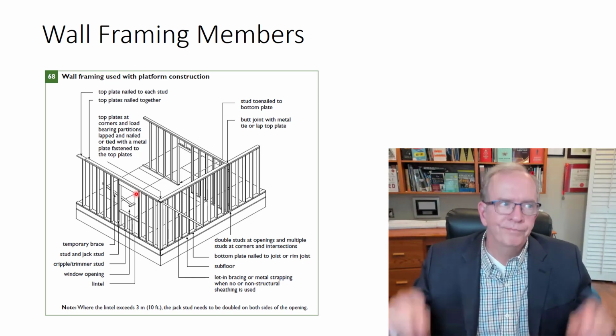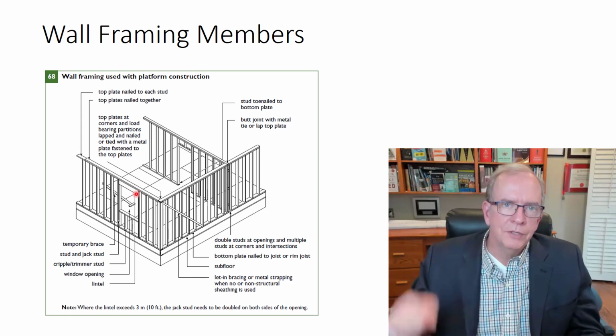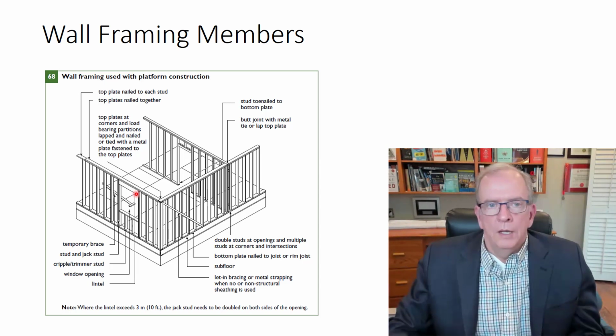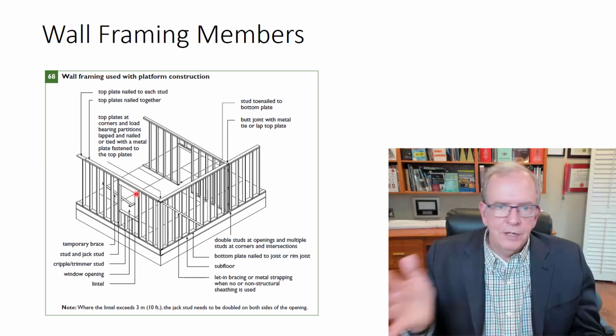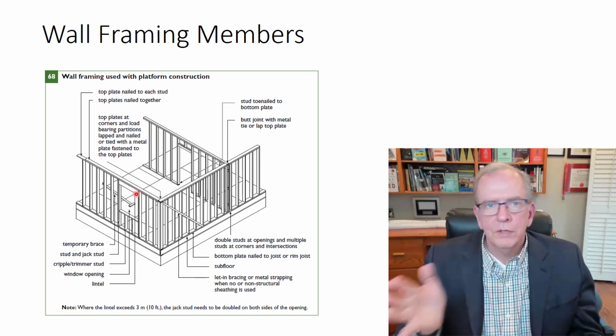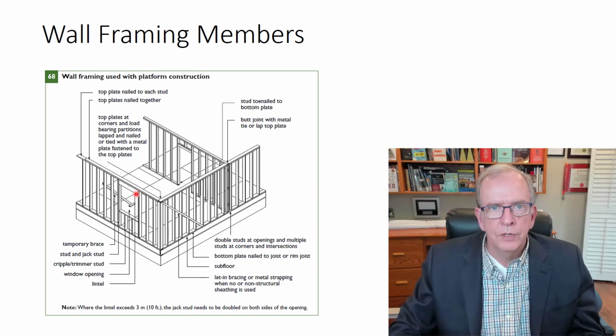Usually when you're a professor in construction management like I am, you really sort of take this hard line that you got to call it a lintel. What I usually tell my students that are going out there, fit in. If you're talking to framers, they'll probably say, what are you calling it? A lintel? Call it a header. If you're talking to a building inspector, call it a lintel. They'll know that you at least understand the building code from that perspective.